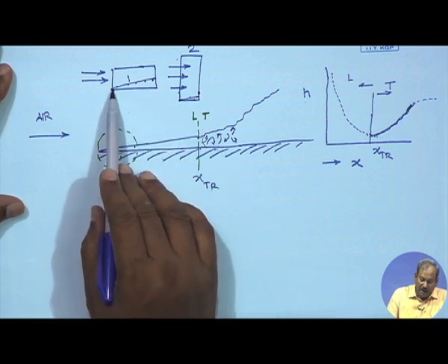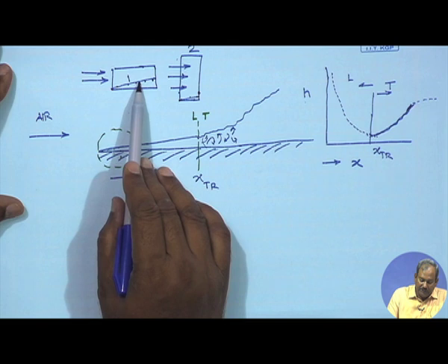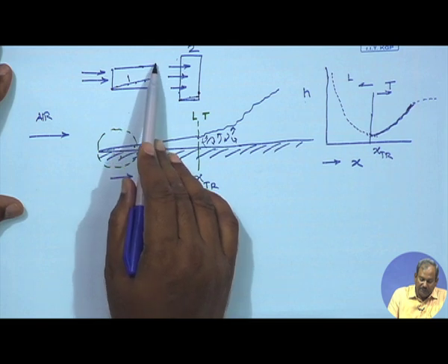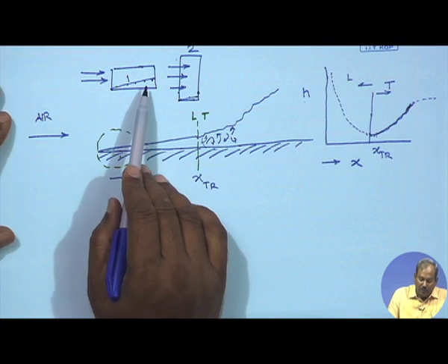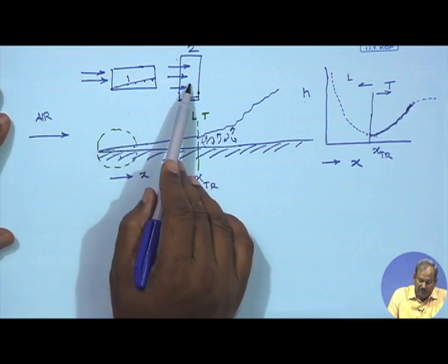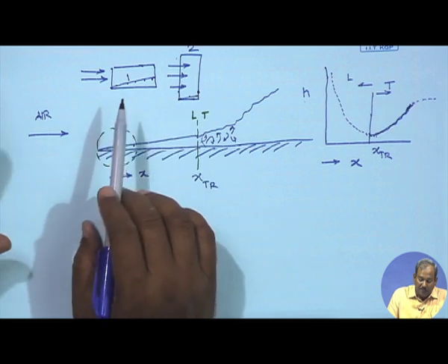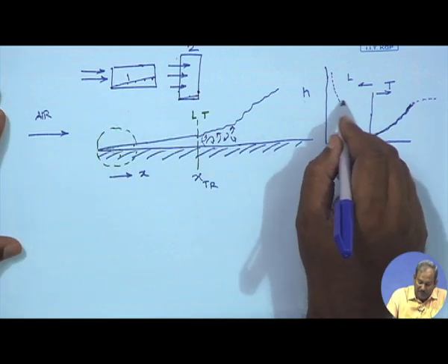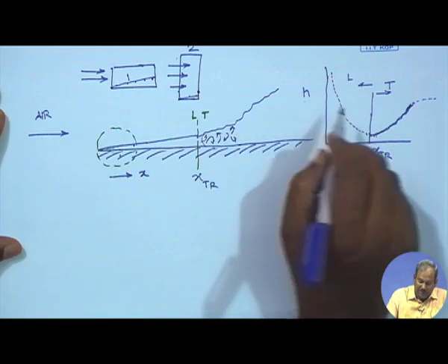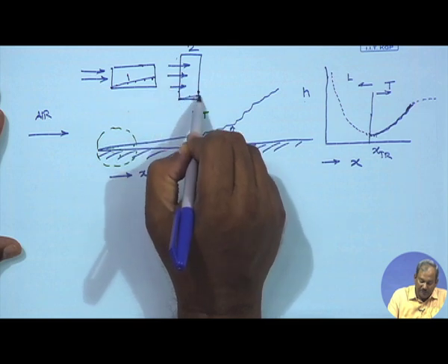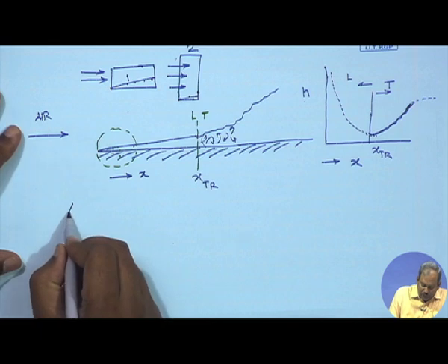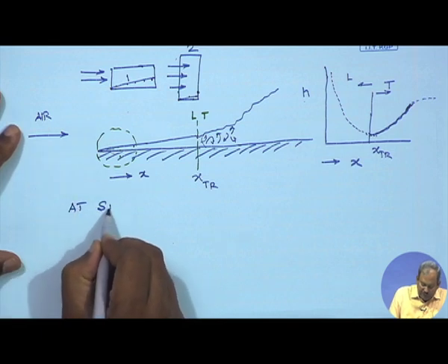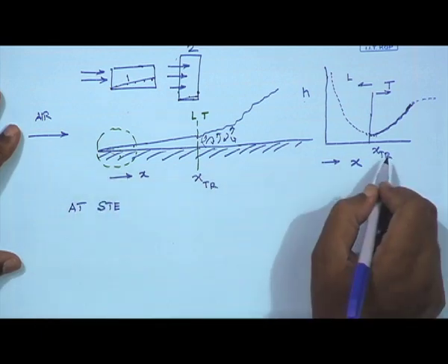That means after passing through some distance it becomes turbulent. Then a clear cut solution of whether to have it in this way or in this way cannot be made. But if it stays laminar, if you are working in this zone, then it's always better to have the smaller side exposed to flow. So once you understand this, there's nothing in this problem.